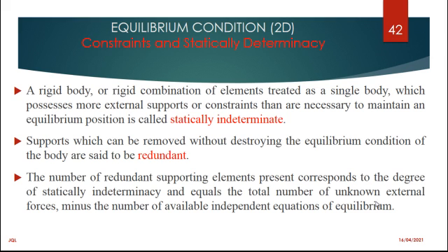Supports which can be removed without destroying the equilibrium condition of the body will be called redundant, but they are useful. When you do your calculations, you don't need those members, right? But you would need the redundant members for the purpose of stability.